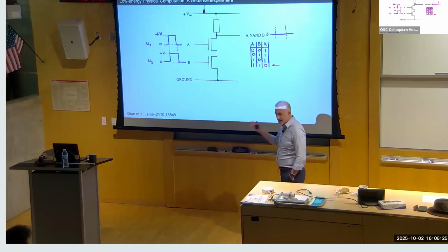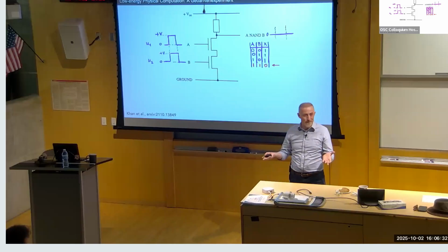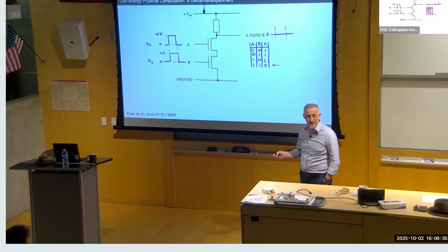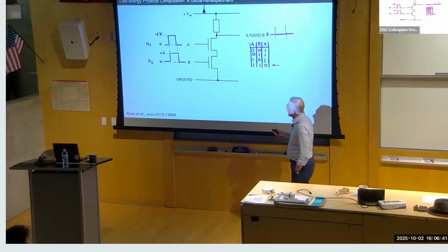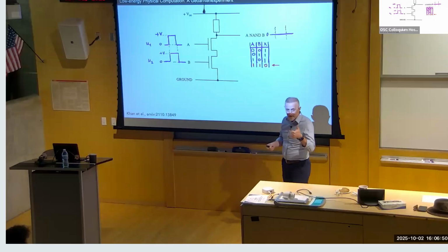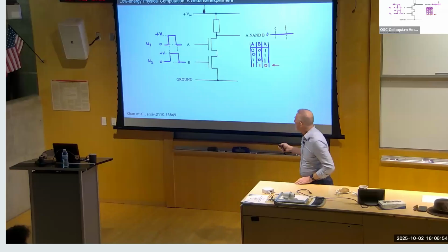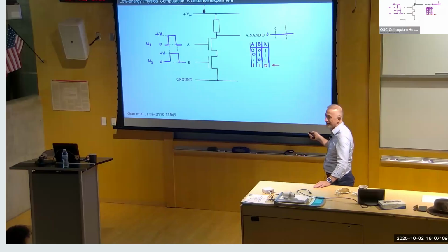And so really this is a function generator, but this function is bit valued in the input and bit valued in the output, but at the end it's a physical stimulus that encodes these bit values, right? So I'm going to ask the question, can I still compute this function accurately as I decrease the voltage of 1, the bit 1. From 1.5 volts, I decrease it, and standardly you would think, well, if I get down to a level of voltage that cannot be distinguished from 0 with respect to the thermal fluctuations in voltage that I'd expect in this device, I should be constantly making errors here.